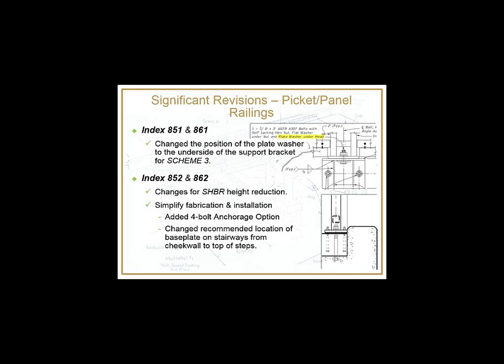But we've also added a 4-bolt anchorage configuration, as you can see on the lower right-hand side, and we've moved the mounting location on stairways from the top of the cheek wall to the top of the step, which provides better anchorage and possibly allow us to reduce their anchorage depth in the future when we move to the new adhesive anchor design criteria, which should be coming out later this year.